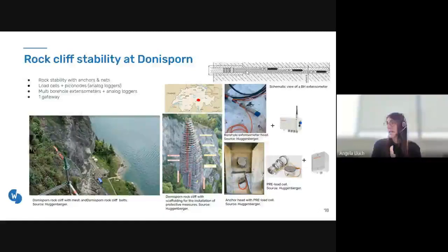These sensors, in this case, there were 3 sensors. Each of them measures the relative displacement of the ground with respect to the measuring head at different lengths or depths. The displacement transducers are, in this case, located in the measuring head. So the idea was to see this elongation of the ground.